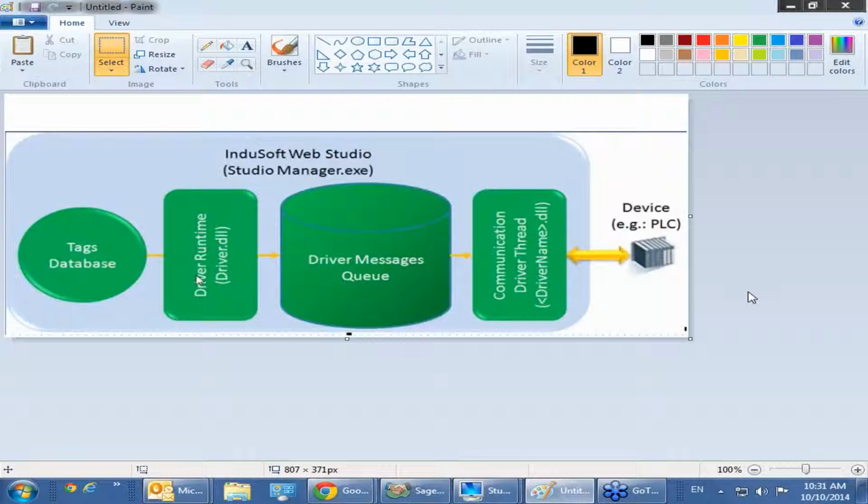Do you want me to switch to you to be the presenter, Robert, so you can show how to configure slave modules? For the ZT2551 and ZT2571, those are ZigBee slave modules. You connect with the utility via COM port, or Ethernet if you have the 2571, to set the PAN ID, the node ID and the address of the module. Once it's configured, you can connect it to the host. You would set it for the same channel ID. So if your slave devices were some sort of I/O module other than the ZigBee I/O modules.